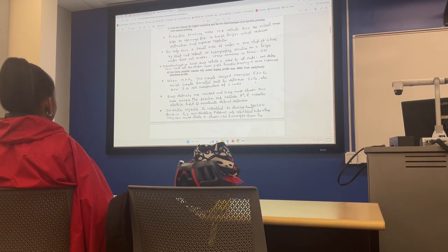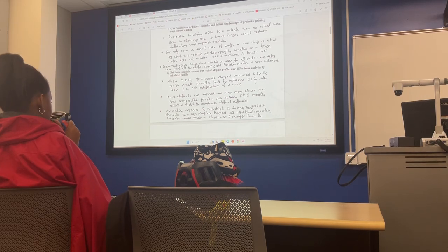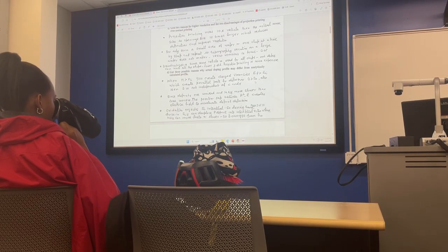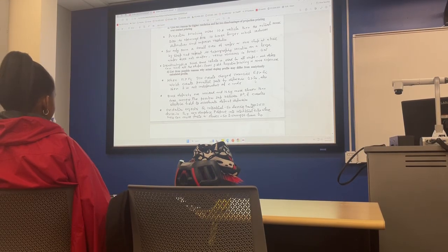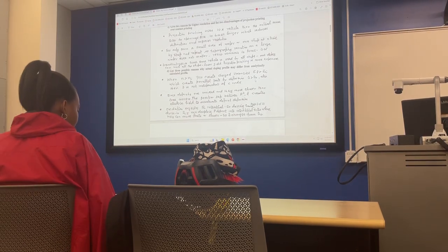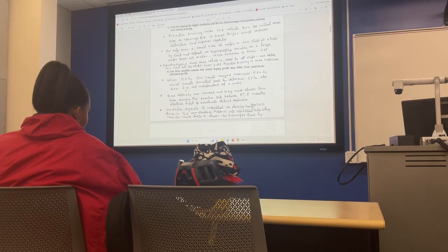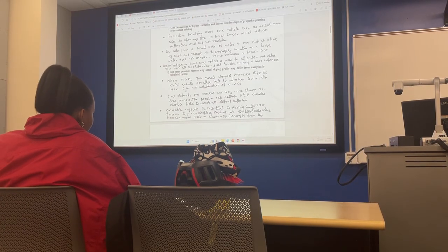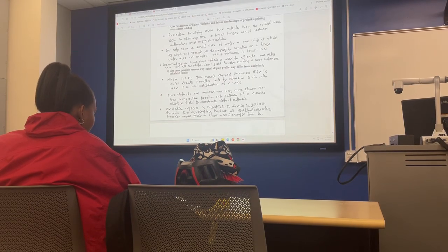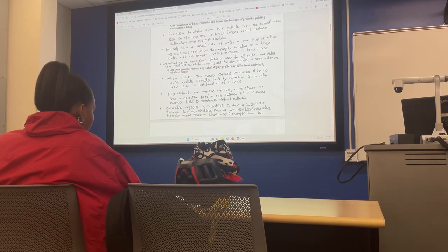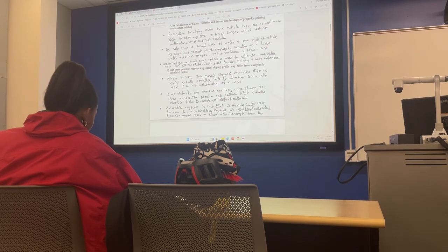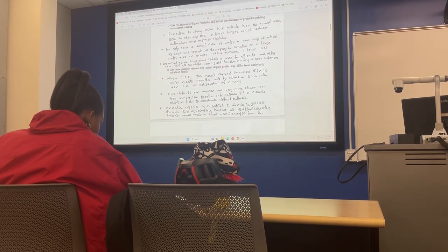So you have another channel for diffusion, so your effective diffusion is greater than the diffusion when there were no charged vacancies. But in our analytical calculation, we didn't account for that. We just assumed D was constant, independent of the doping or the position. That was a major assumption, which seldom actually holds. You get some profiles with very high doping, so you run into this problem. That's why you may see some difference, and your diffusivity actually becomes higher than if this was not the case.